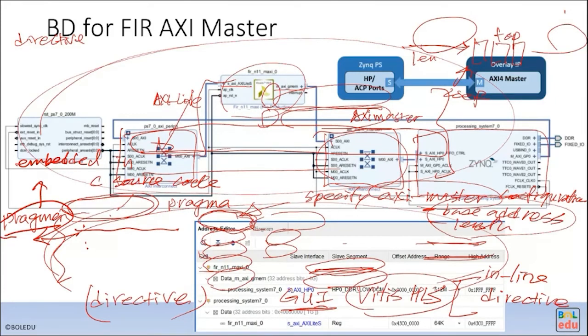Okay, remember here there's 64-bit, and this here is 32-bit. That's why, and the frequency may run differently. So although this is an AXI master and this port is an AXI master, they simply cannot connect directly. It needs to use this interconnect. This one is obvious because it does AXI master to AXI lite protocol translation. So that's how you connect to the whole system.